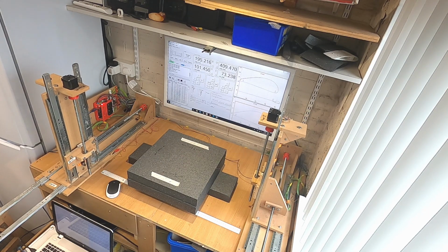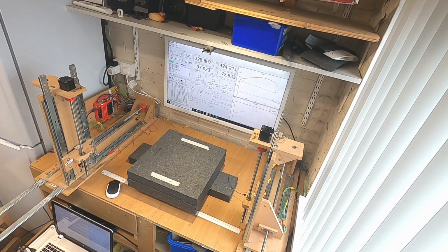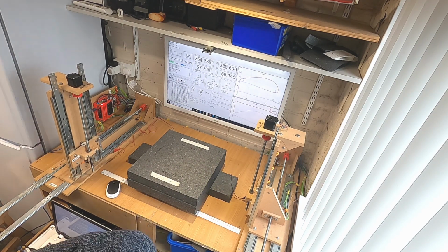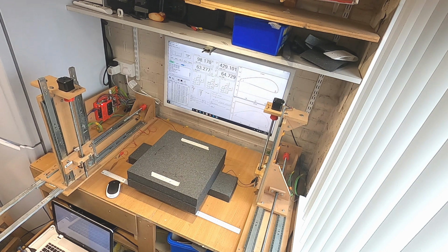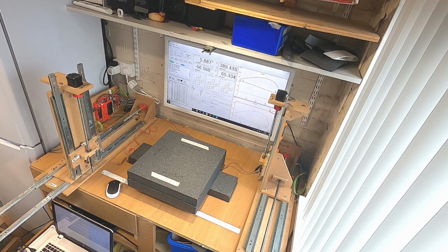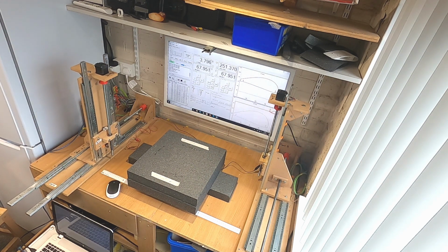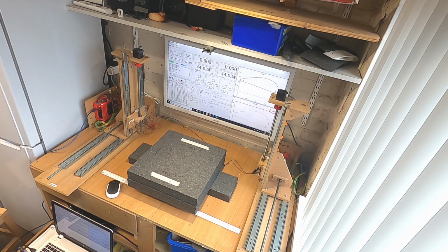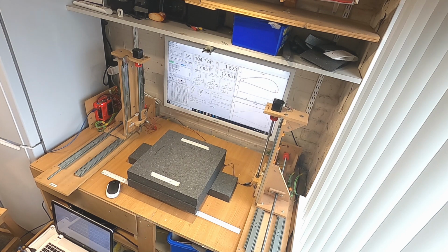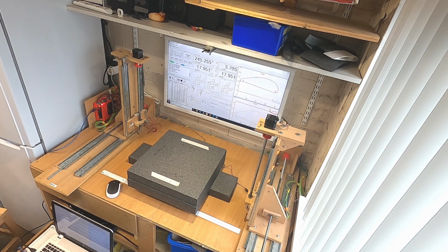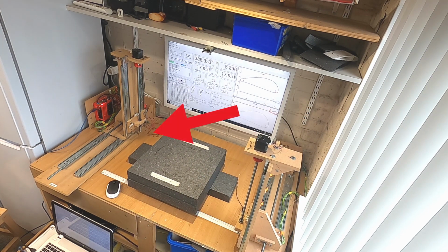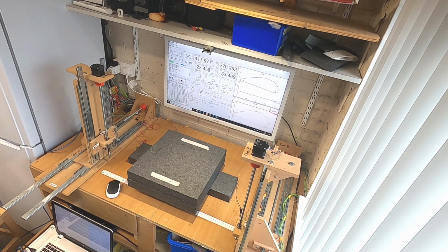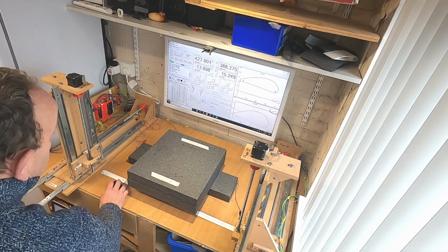So here we are cutting the wing cords for this forward swept wing design that you'll see in a minute. And as you can see, the draw slides are quite extended. And actually for this design, not for this actual part, but I had to put longer draw slides in and also longer threaded rods. It hasn't got the longer threaded rods in at the moment, but that's the beauty of this design, that you can extend it. Now, if you just watch closely, you might see something happen in a minute on the, there we go, the actual fishing wire broke.